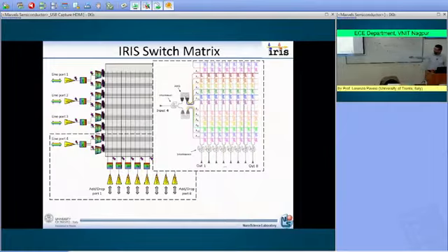Then we have the switching nodes, which are our add-drop microring resonators that should be tuned in order to determine whether a wavelength should go through or should be dropped from the switching matrix. Okay? And therefore now we need to understand the working function and see how we have implemented all those different functionalities: the interleaver, the demultiplexer, and the switching node.